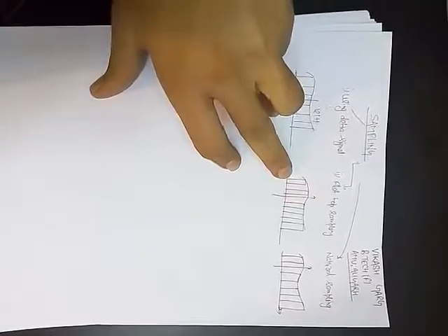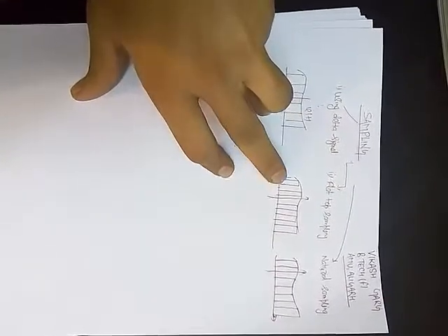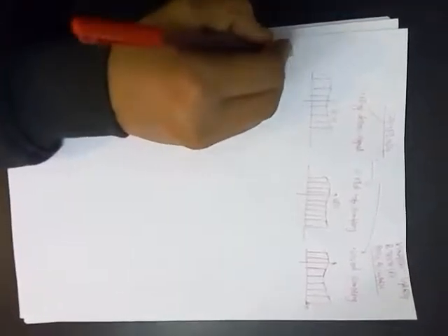So clearly one can say that for flat top sampling, what we should do is take a rectangular pulse and convolve it with the original analog signal, that is x(t). And for natural sampling, similarly we take a rectangular pulse and simply multiply it so that its amplitude takes the form of the original analog signal. So let's continue with the first one, sampling using delta signals.